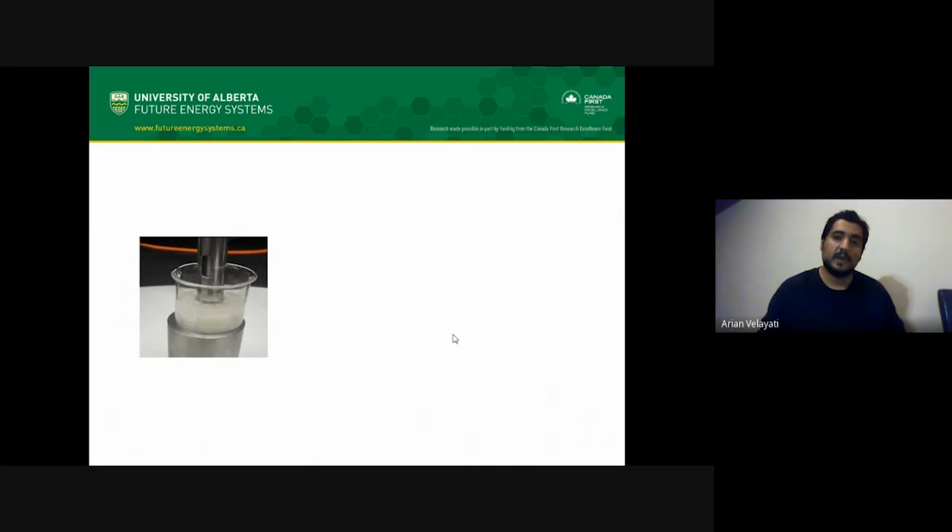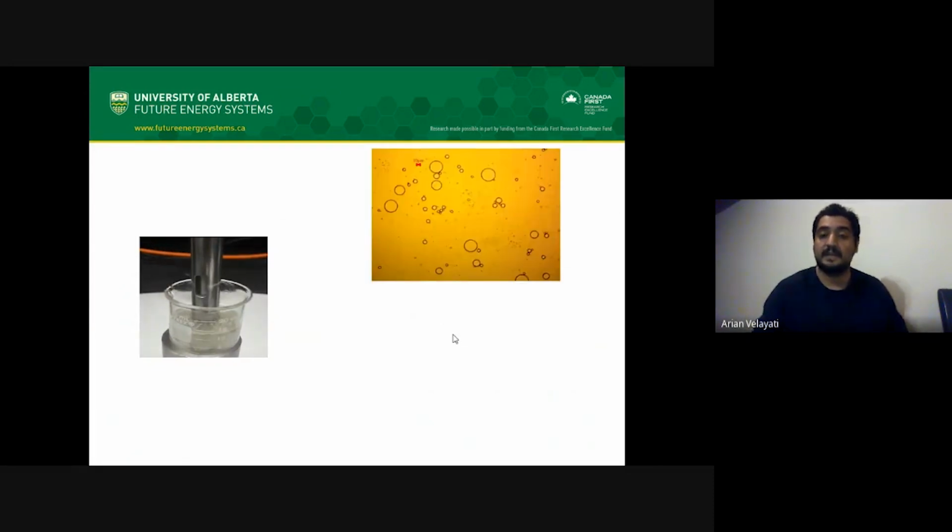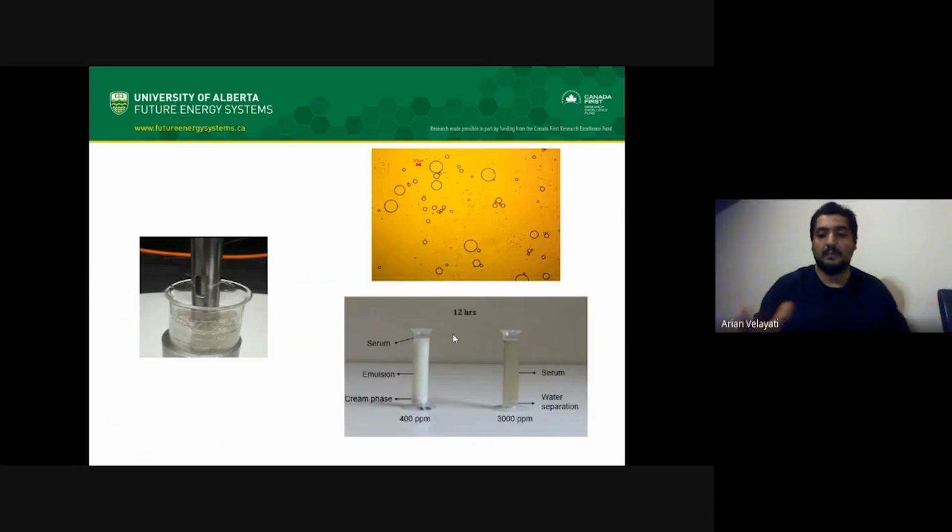It is not easy to have access to the bitumen from the reservoir. And even if you have access, there's always the risk of fire and explosion and other safety risks. So we are using green emulsifiers and other components to have a reliable model. This model emulsion should mimic some specific properties of the actual emulsion that is formed inside the reservoir, including the droplet size and droplet size distribution, and more complicated ones such as the viscosity, or how it flows, and the stability of the emulsions.